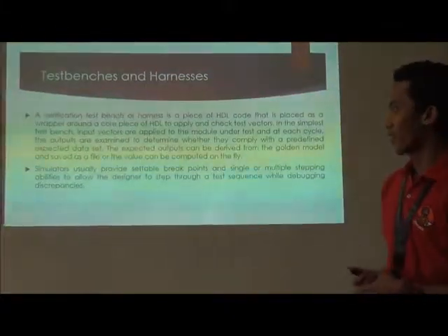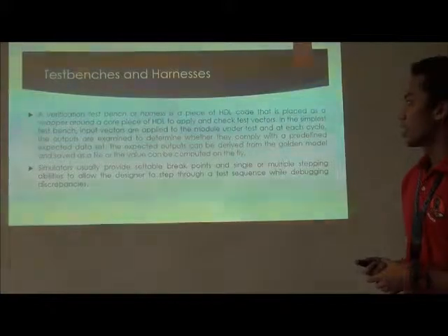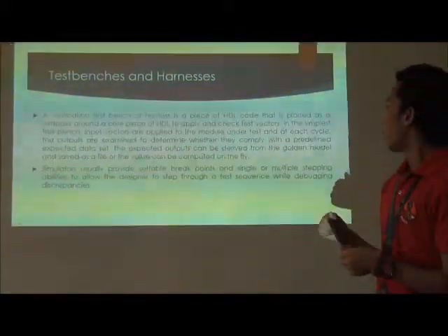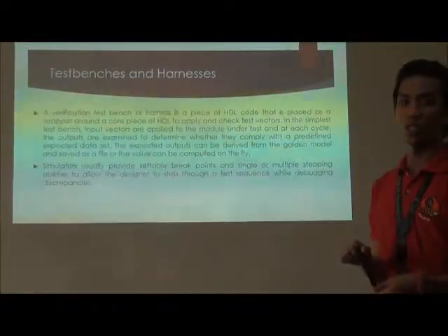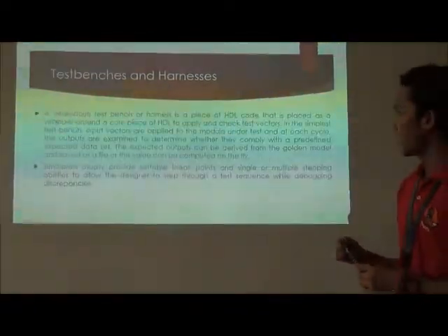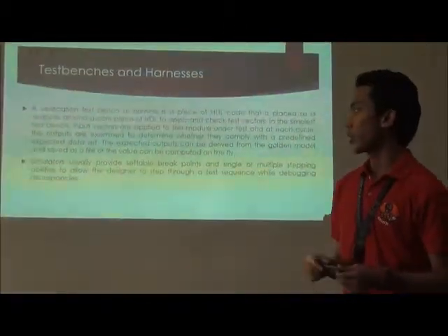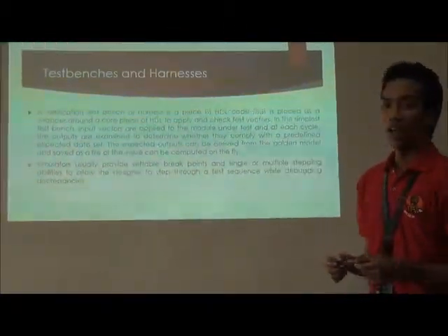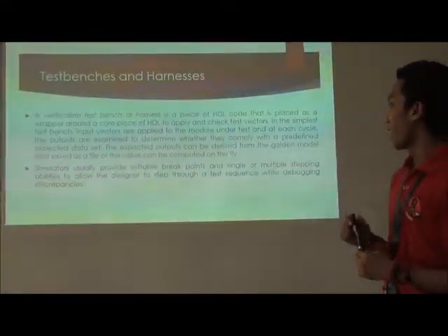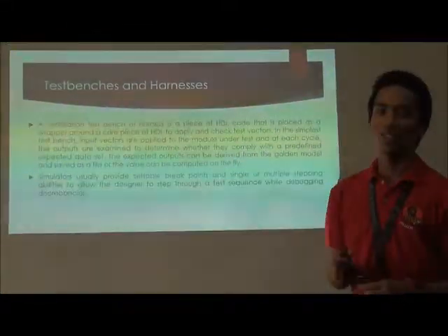So we have also the test benches and harnesses. A verification test bench or harness is a piece of HDL code that is placed as a wrapper around a core piece of HDL to apply and check test vectors. In the simplest test bench, input vectors are applied to the module under test, and each cycle, the outputs are examined to determine whether they comply with the predefined expected data set.